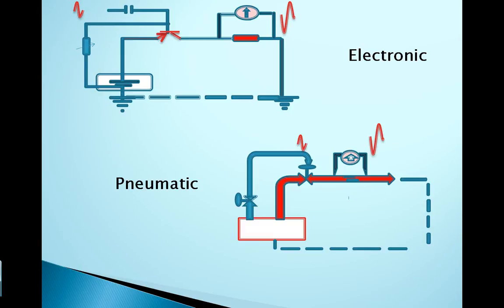Now if the transistor is completely shut, there's no current flow, and therefore all the voltage is across the transistor. If, on the other hand, the transistor is now opened and current flows, then there'll be a differential pressure, or in this case potential difference, across the resistor, which will drop some voltage, and the rest being across the transistor.